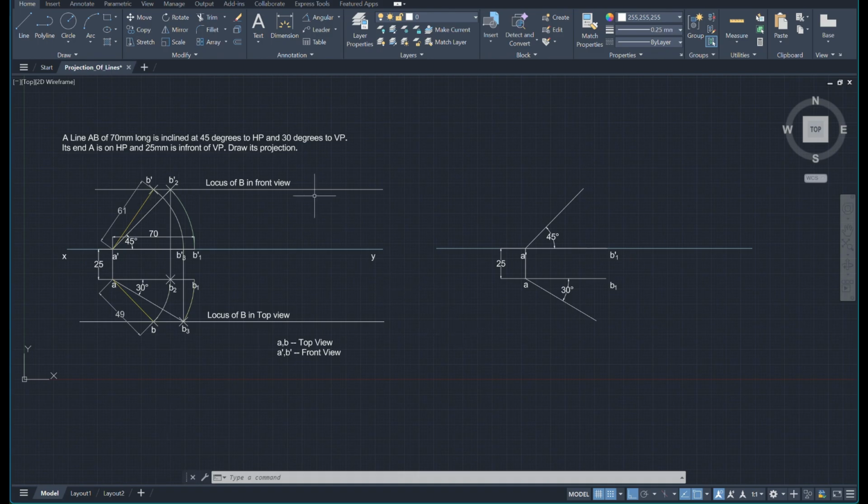As I said, we need to take the compass and make arcs, right? So instead of a compass, in this AutoCAD, we will use circles. Take this point, from this point to this point. Now you got this intersecting thing, right? So you have to plot this intersecting point here.